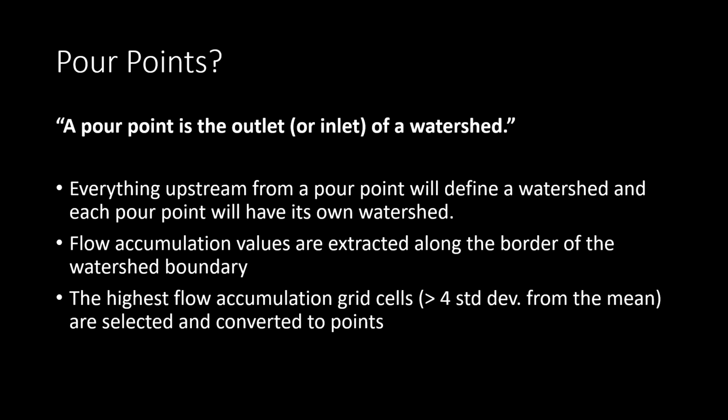points once they're created. Accurately capturing the locations where flow paths enter and exit your watershed will ensure that all follow-on ACPF tools are representative of the land area draining to your watershed outlet. Failure to provide accurate pour points will likely result in an inadvertent inclusion of land area from neighboring watersheds. Additionally, pour points are a required input to the Stream Reach and Catchments tool to ensure that neighboring watersheds are not included in the hydrologic boundaries that are created as an output of the tool.